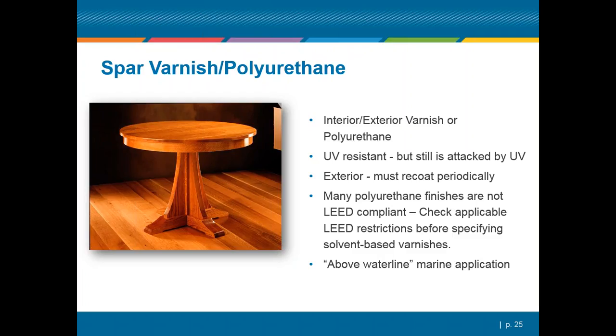That's kind of where they got some of their first entrance into wood finishes, back in the day whenever speedboats and so on were built out of wood. These spar varnishes were the finish coat that were desired in that particular circumstance. They're UV resistant, but they can still be attacked by UV. And anytime you're using a clear finish, if you're doing exterior wood doors or so on, just know that's going to be a maintenance issue.